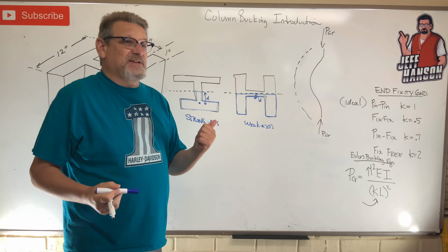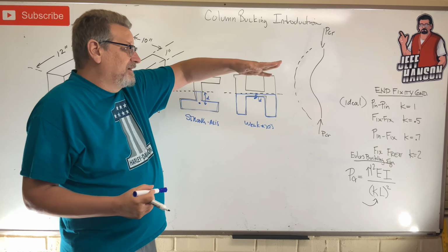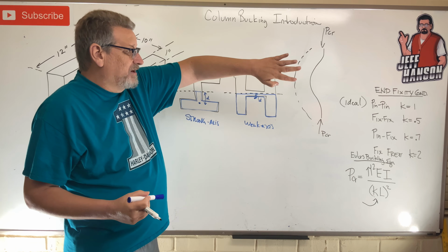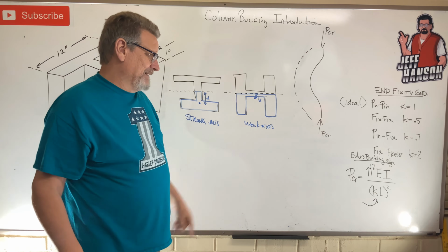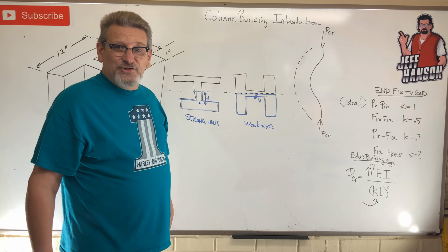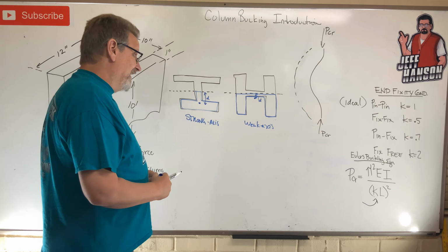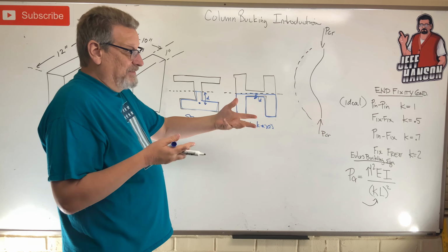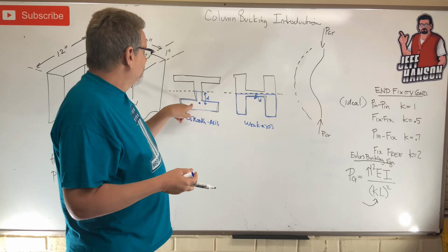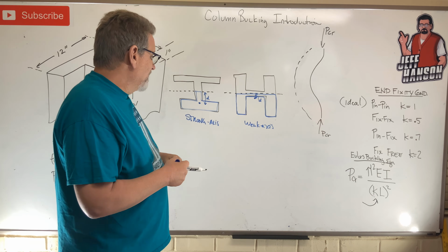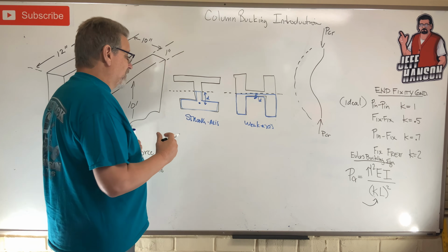If you go on a job site and you see somebody putting a beam up and they're welding it horizontally, let's say, in the H direction, you need to go up there and tap them on the shoulder and say, hey, you're installing that wrong. It's not strong that way. If you ever mess with an I-beam, it'll sag, it'll bend if you pick it up like this versus picking it up like that. Now let's just demonstrate that real quick.